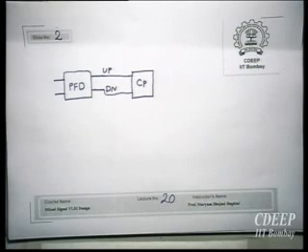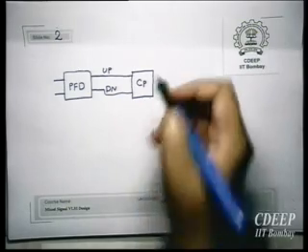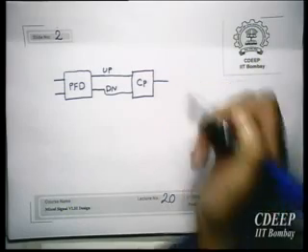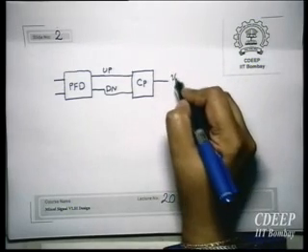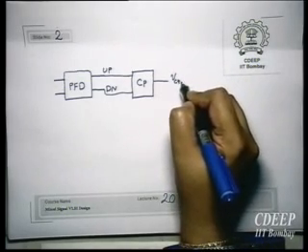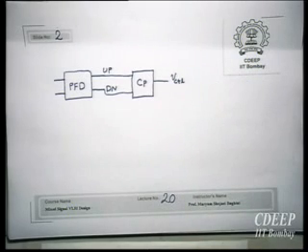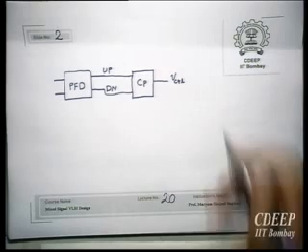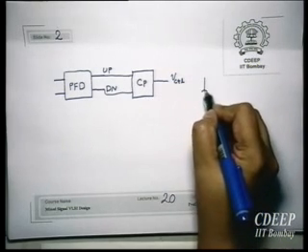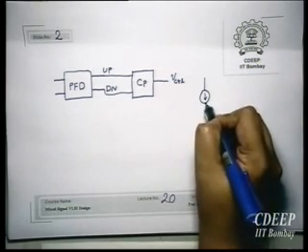So this charge pump actually constitutes two current sources, right? And then at the output, we will get a voltage, which is the control voltage of the VCO. Now, practically we use this up and down to control the charge pump in this fashion.